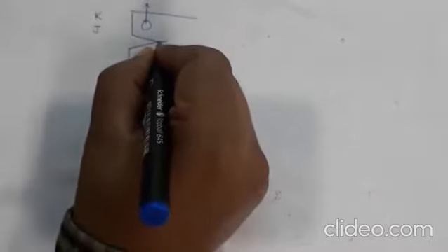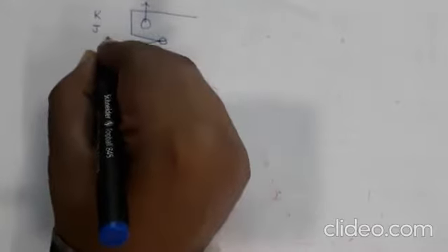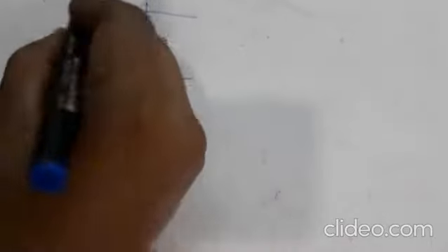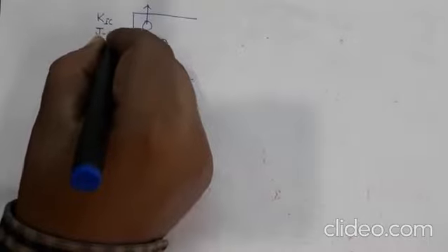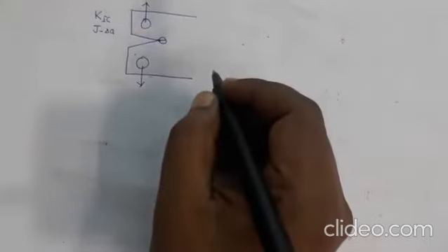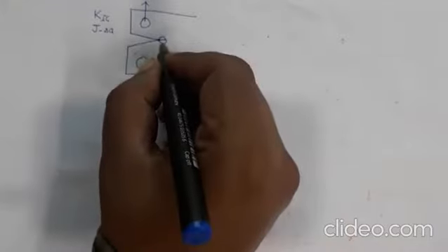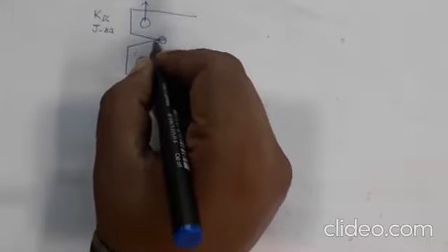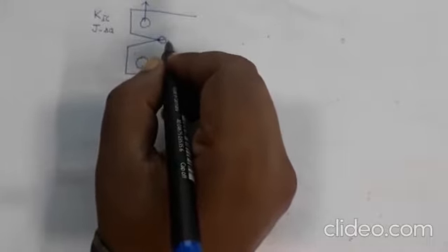To create this sharp crack, we apply some fatigue loading before doing the K1C fracture toughness test or the J versus delta A test, which we studied in the fracture toughness chapter. Why do we do this? Because we can do this kind of crack growth using cyclic loading under stresses which are smaller than the yield strength of the material.